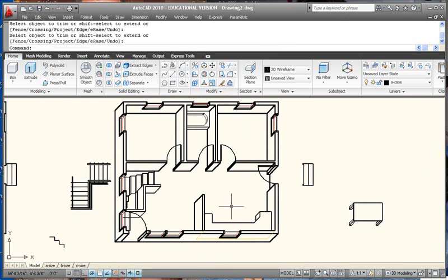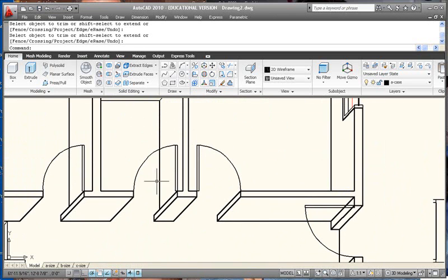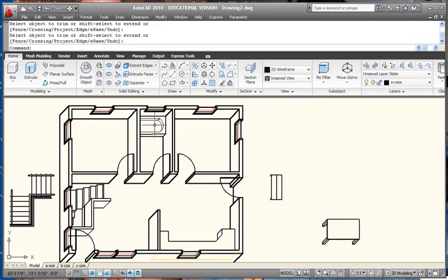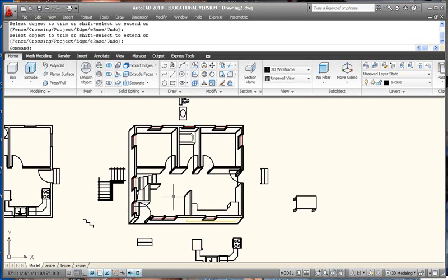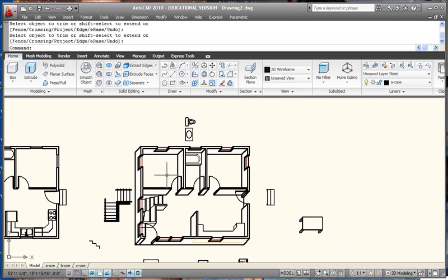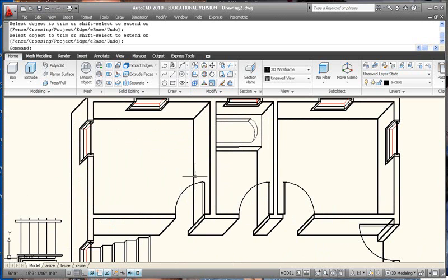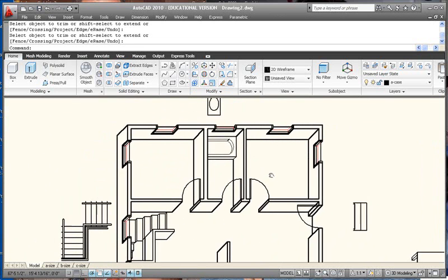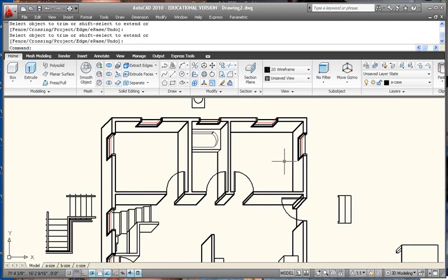What I'd like you to do is get to the point where you have the floor plan represented with all the openings in the doors. You can also show the doors with the door pattern and the height of the door sliced at this height. Show all built-in fixtures. So this would be countertops, any plumbing fixtures that are built in, stairs, walls. And the next step would be to go ahead and put in some furniture to show what's going on in these spaces. Draw a bed, a cabinet, or anything else that you want to put in, chest of drawers, things like that.